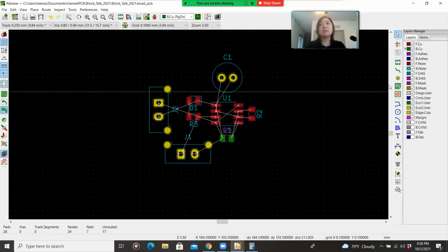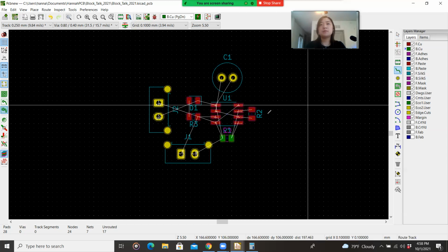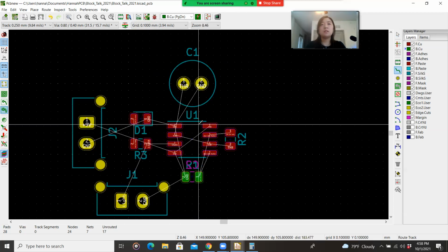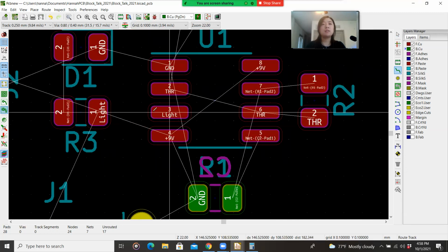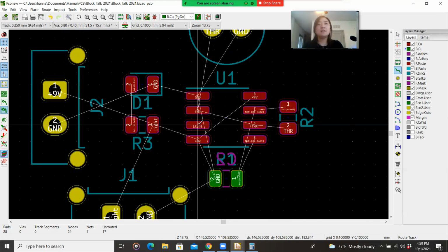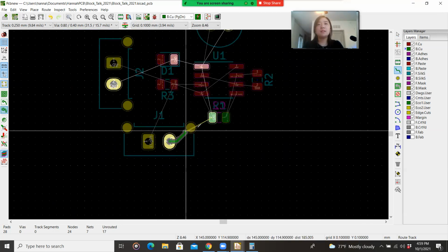So how do we go about doing that? Well, we go to this right side and we click this trace. Okay, so then we want to connect things. And so it's similar where we just kind of connect the dots here. But almost all the time, what KiCAD provides you as its default path, like let's say this to this.